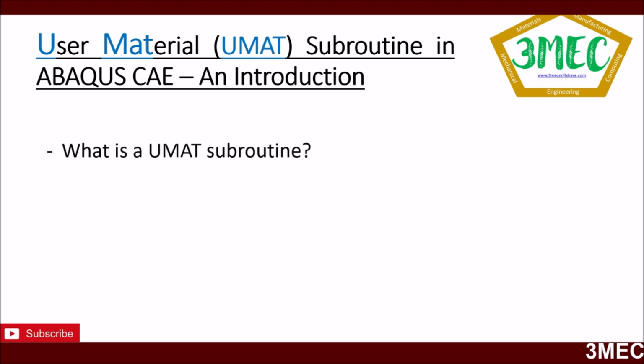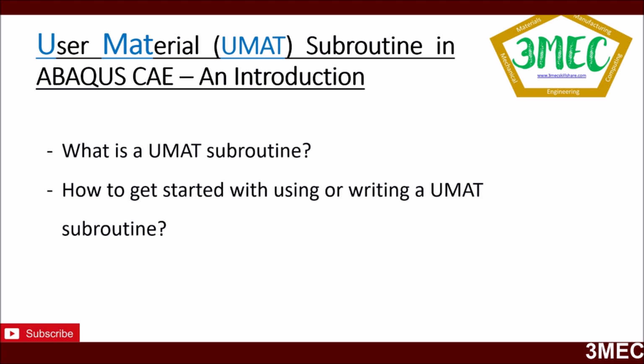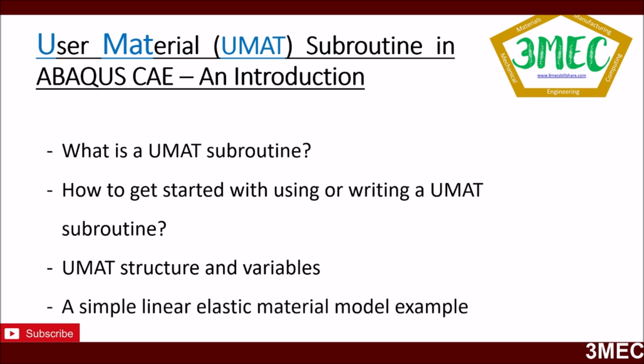So I will start with what is a UMAT subroutine, then how to get started with using or writing a UMAT subroutine, then I will try to explain the structure of UMAT and what are the variables that are involved. Some are the inputs which are coming from ABAQUS CAE, while some are the outputs which have to be computed in your UMAT subroutine and then transferred back to ABAQUS CAE. I will explain those, and finally a simple linear elastic isotropic model example.